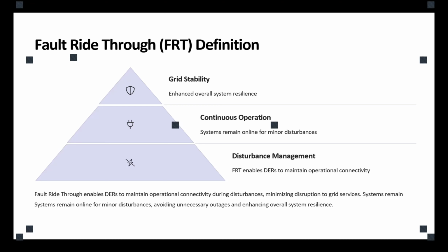If we don't consider that, every time any incident happens, the protection system of the inverters, which is much faster than the conventional generator, would seize the power, and not just seize the power, would disconnect the inverters from the grid because it wants to protect the inverters. And if that happens, anytime an incident happens we are going to lose a huge amount of generation. Power balance is disturbed, the system goes to instability. Worst case scenario, blackout.